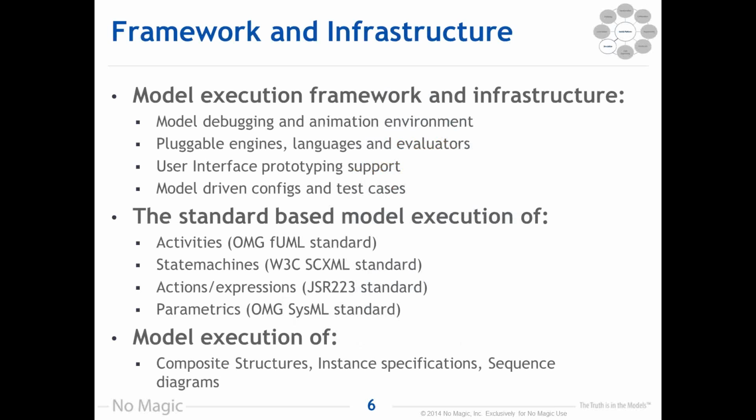Now let's talk about standards. So first of all, activity simulation inside the tool is based on the Object Management Group Executable Foundation for UML standard, fUML. State machines are based on the State Chart XML standard from W3C. Then we support the actions and expression standard JSR223 for scripting languages, and of course SysML parametrics. Besides standard-based model execution, we also provide composite structures execution, instance specifications, and execution of sequence diagrams.